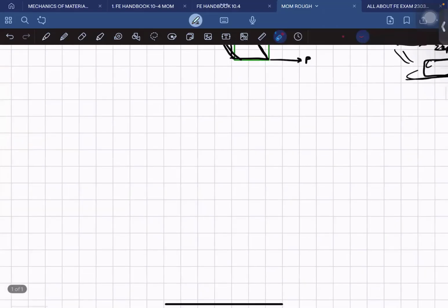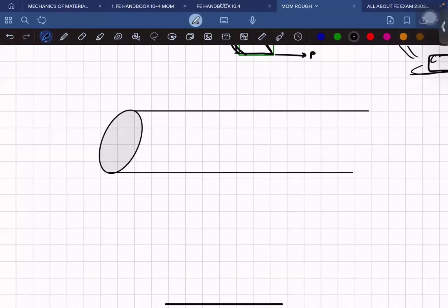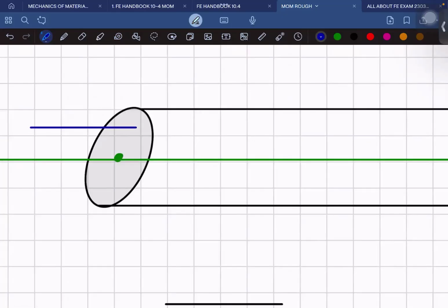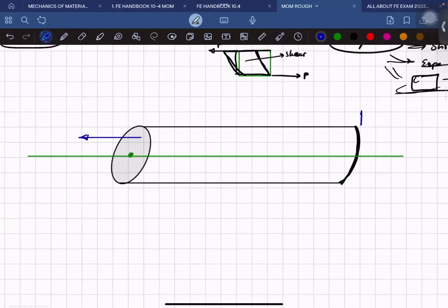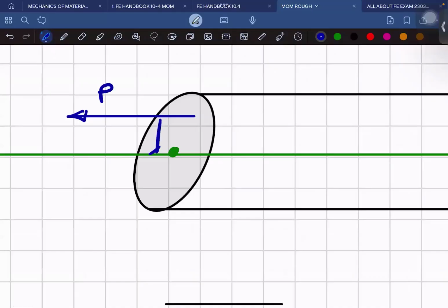Yeah. Actually, your concern is valid, I agree. Suppose this is my cross section of a rod. This is my rod. Your question is, suppose this is the center of the cross section and this is the axis of the rod, and the load is applied here. If I fix this end on a fixed plate and pull it somewhere here, that is with some eccentricity, it is a combination of tensile load as well as some bending developed.